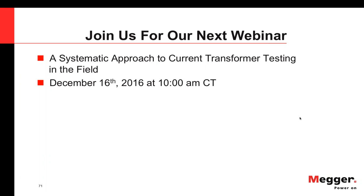Do you see a certain piece of equipment failure resulting in 8th order harmonics? That would typically be a sign that a rectifier somewhere has opened. I don't know what particular piece of equipment would do that, but it's definitely a bad piece of equipment there if you have significant 8th order.